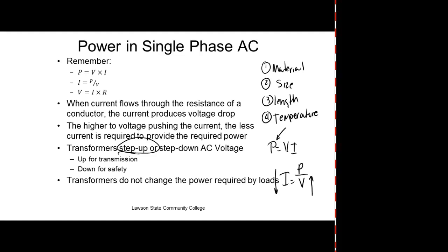So if it's not 240, where's the plug for your refrigerator? It's probably behind your refrigerator. Your refrigerator runs on 120 volts, right? Where's the plug for your water heater? If you've got an electric water heater, it doesn't have a plug. It might have a disconnect, but it doesn't have a plug. So that's hardwired. If you've got a totally electric or even a combination unit, an air conditioning HVAC system, it's hardwired. It's got a disconnect out there. That's required, so if they go out there and work on it, they can pull the power on it, but they don't have a switch on it.